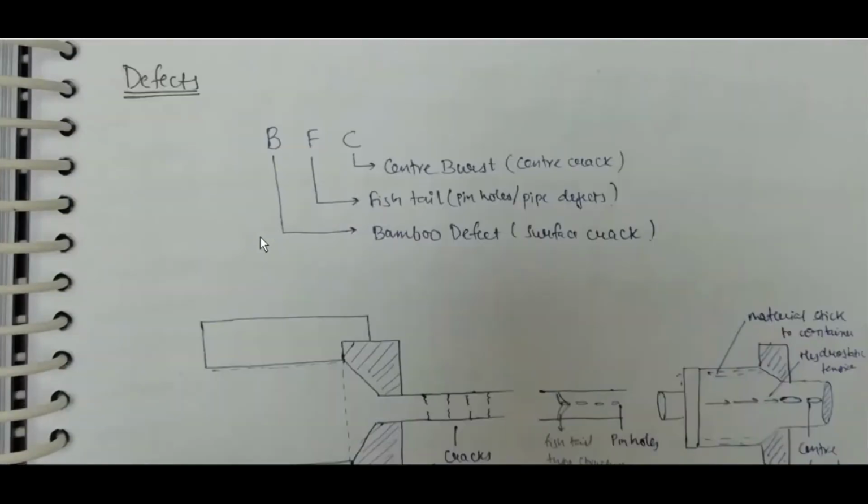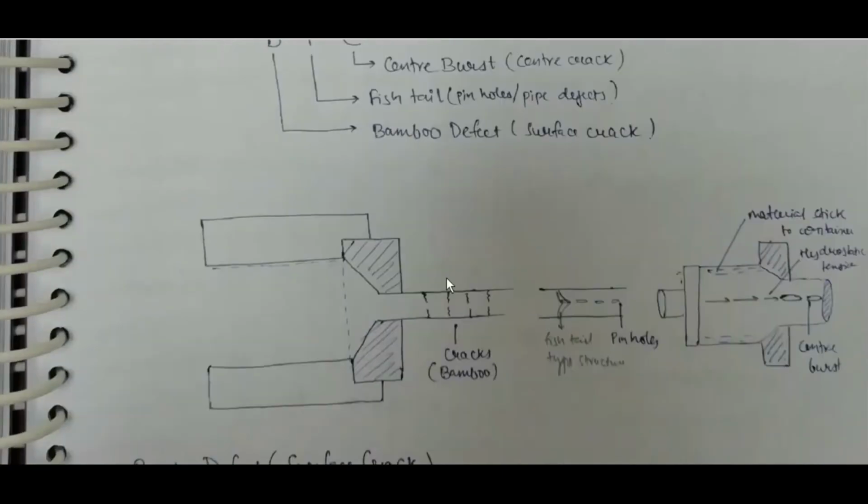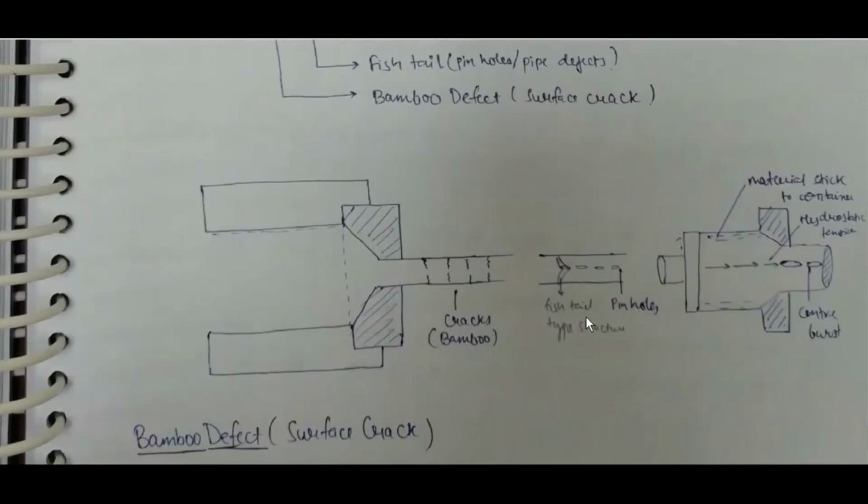Forging is a process in which given raw material is compressed with the help of die to get final finished part by plastic deformation. Forging can be done in a hot or cold working operation. Material is always considered as incompressible, that is volumetric change is zero.